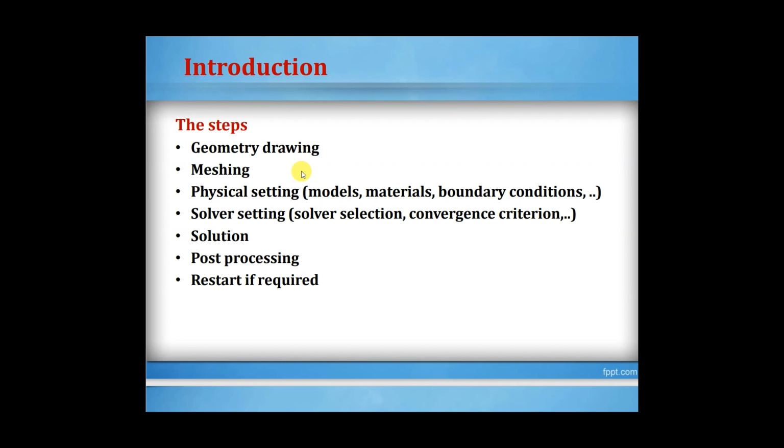And some people ask, do we have to model it in Ansys or not? There are two ways. You can model it in Ansys, but most of the time I personally do not do it unless the process is short, unless the modeling is simple. But if it's complicated, it's better to go for software like SolidWorks, like CATIA, like Inventor. By using them, you will have a 3D design. By saving them with the IGES suffix, you will be able to insert them in Ansys.